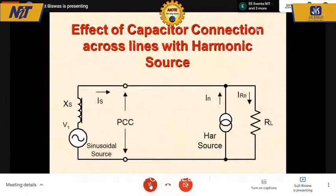Okay. Now we are going into the real aspect of what is the effect of connecting capacitors across the lines with harmonic sources. This will be very interesting. This is my sinusoidal source, because right throughout I've assumed that my source is sinusoidal, which is a very good assumption, because most of our generating equipment, the alternators, do create sinusoidal voltages. This is a reactance in series. The reactance in series includes the synchronous reactance of the generator, the reactance of the supply system, the reactance of the transformers, whatever is connected everywhere.